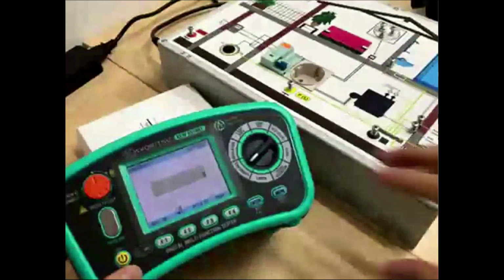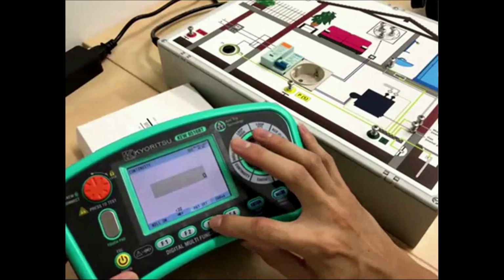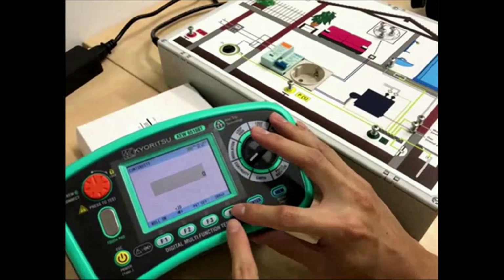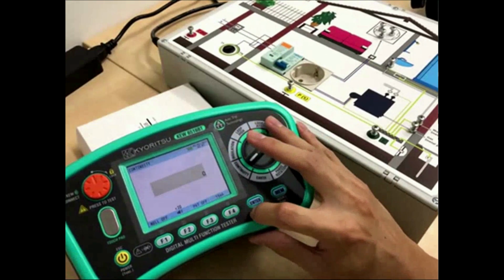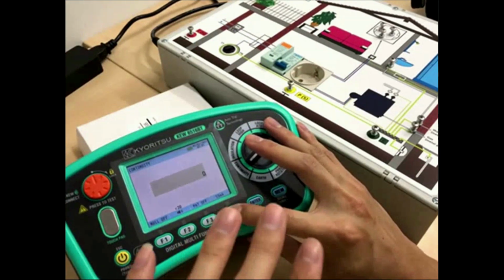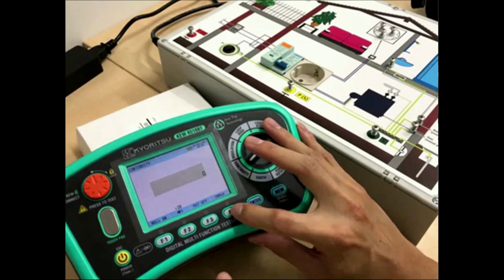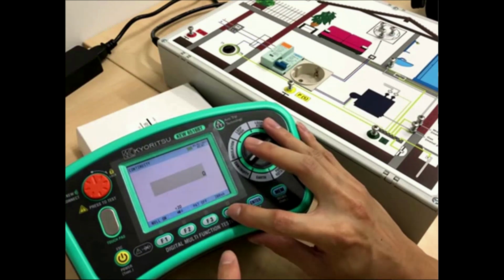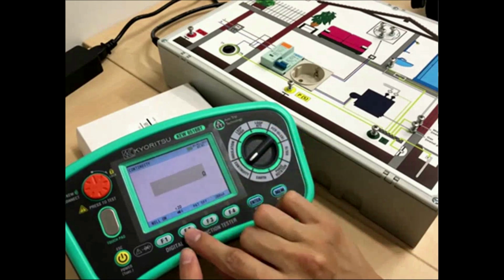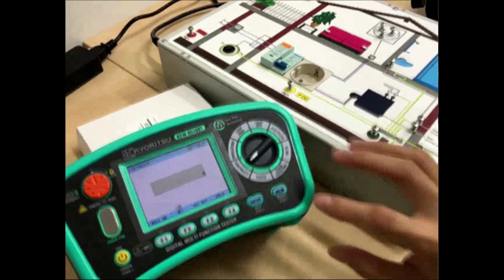Okay. Now in this, we don't have an appliance here. We set it off. And then this one is 200 milliamps and 50 milliamps. For continuity test, 50 milliamps is not so important. Because our competitor has it, then we have it. 200 milliamps is enough for continuity test below 2 ohm resistance. Now I show you how to test it.